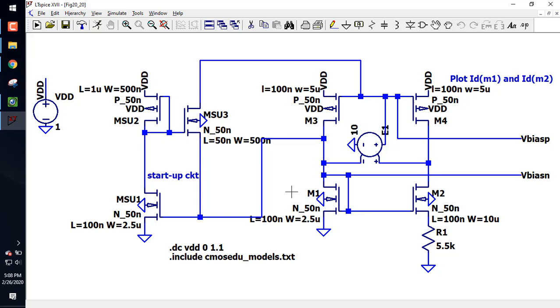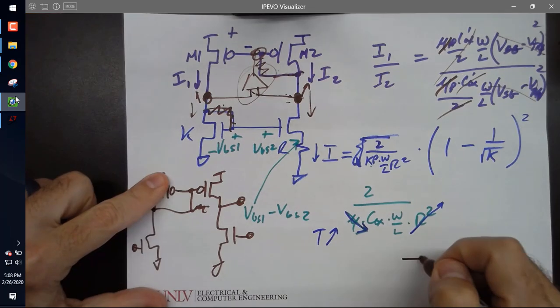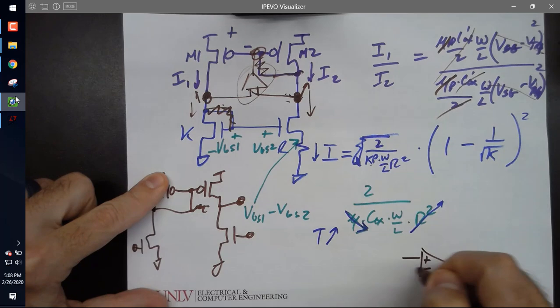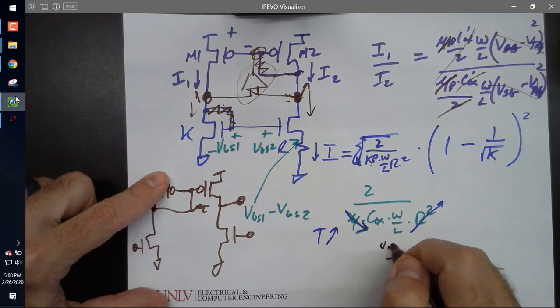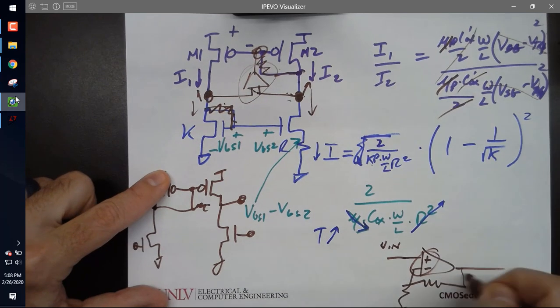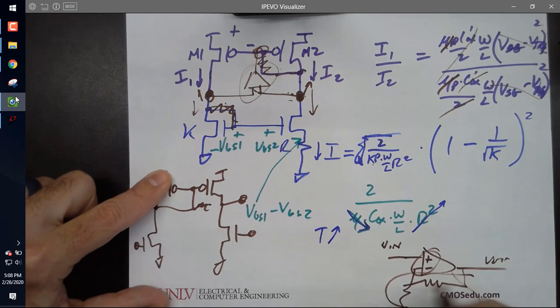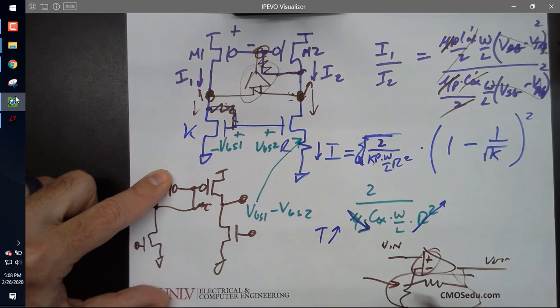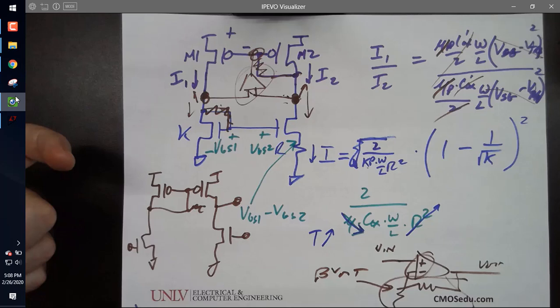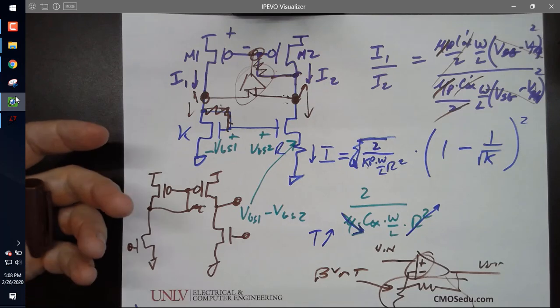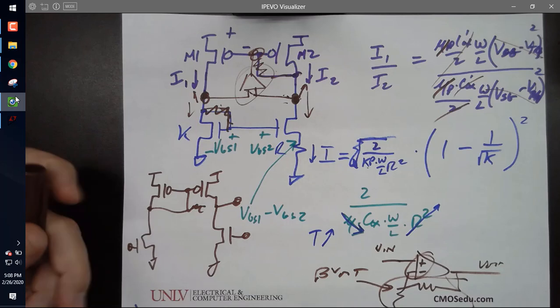When I took feedback and control, I'm like, what the hell? It's just a bunch of blocks. And then I got out and I started working. I figured out that you probably have seen me do this, where I do this. This is a great example of a feedback control system, where this is your in, the in. This is where you take the difference. This is the beta network, so this is your V out. So the beta is fed back, and this would be beta V out, which is just the voltage divider equation. And I started, the hell? Why did they teach me that? So I knew all this crap was useful, you know, or give examples like that.